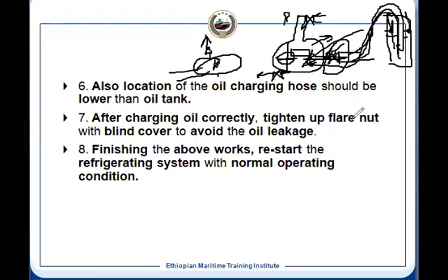Air will be at a higher temperature than the refrigerant. You can vent it here, and once the air is coming out, only a little amount of air will be there. This tank's capacity above the lube oil, that much air will be there, and that can be removed through this. And removal of air is there in your syllabus. I'll come to that. So that is the way air is removed from the system. After that, you can restore the system and run the system.